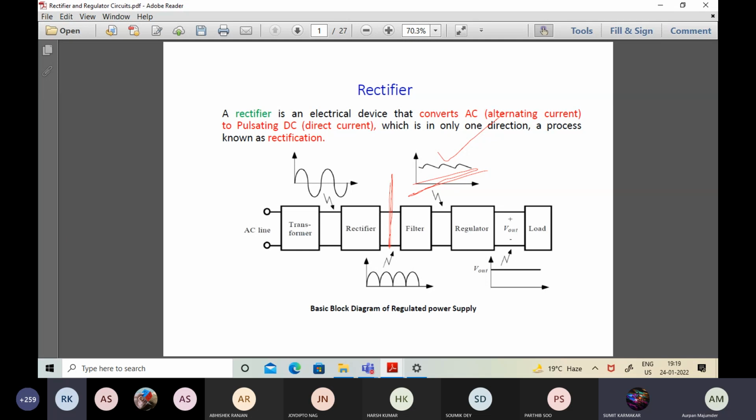What we do next is this: to have a DC power supply, a kind of power supply which should have a minimum level of variation. In what sense are we talking about minimum level of variation? It stands on the fact that if the input source voltage varies, that will not change the output voltage of the corresponding circuit. By output voltage, I would stress that we mean the regulated voltage, or the DC voltage, over here.